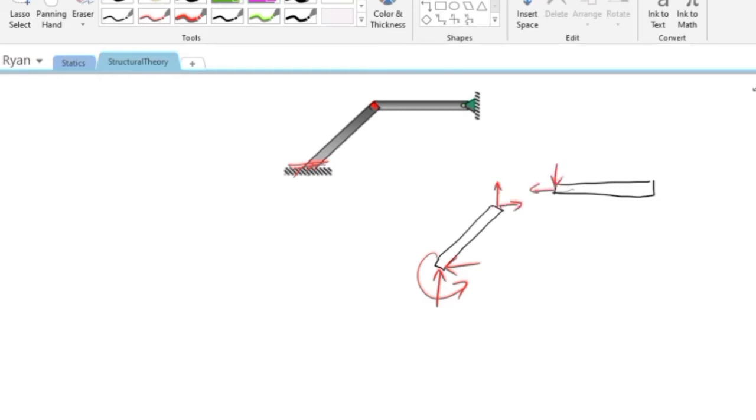And ito din yun. And here, this is a hinge. So, we have here a horizontal and a vertical reaction. So, tatlo yung reaction natin dyan, dalawa yung reaction natin dito, and dalawa yung reaction natin dito. Solving for the relationship of the R to the 3N, we have the number of reactions equal to 7, and your N is equal to 2. So, this is 1, this is 2. So, 7 is greater than 6.